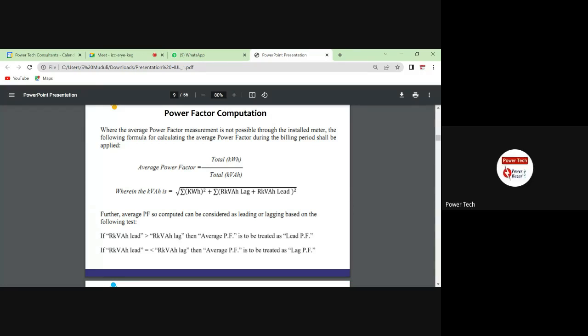Baldev sir, I would like to answer that. In Odisha, what they do is there is a DOM report. If it is a static meter, they take the DOM data. They have all the 5-minute and 15-minute block-wise data sheets in which the register data are there, KVAH billing and schedule billing.